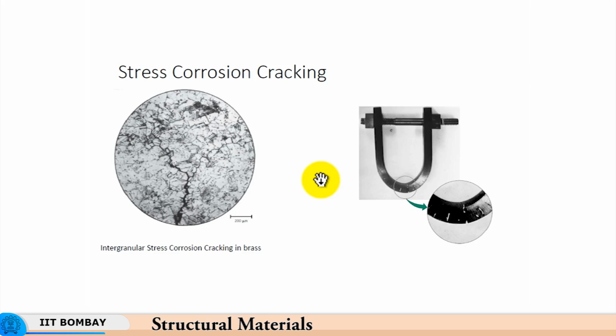So, this region becomes a region of much higher strain. Now, this region is strain free, there is no strain undergone here. As I was saying earlier, one region of the single piece has undergone some deformation. It is more prone to corrosion because here the energy of cold work is stored in the form of dislocations.